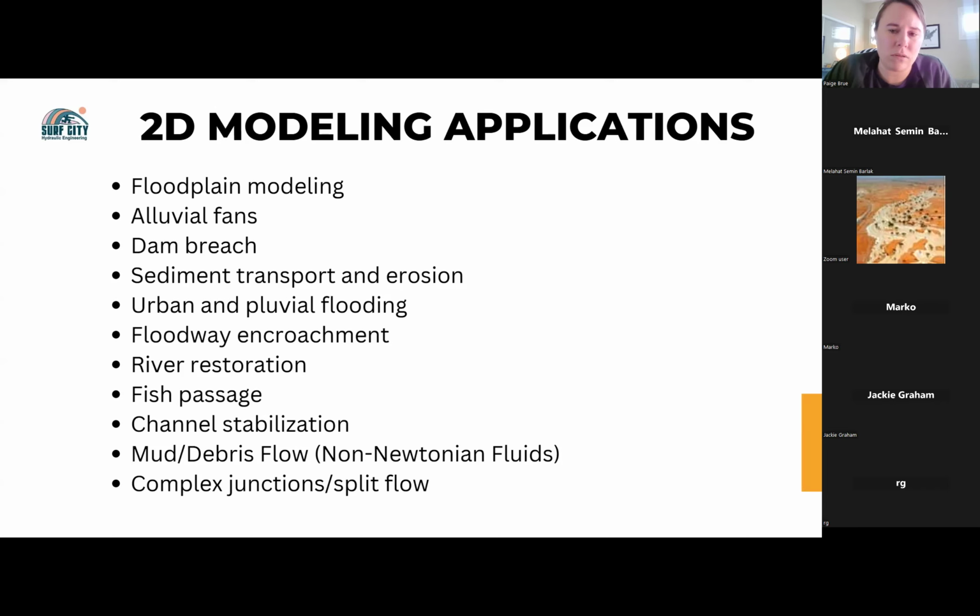Wow. And we don't have anything in downstream, for example, to calibrate and try to arrive to the measured value. So we have just to trust our parameters and go with the value that we think it is reasonable. Yeah, that I've heard that a lot on rain on grid, and Manning's n is a big deal too with rain on grid, because there are those really shallow flows that sometimes people find it difficult to get their Manning's n calibrated correctly. But thank you so much for sharing that experience with yours.